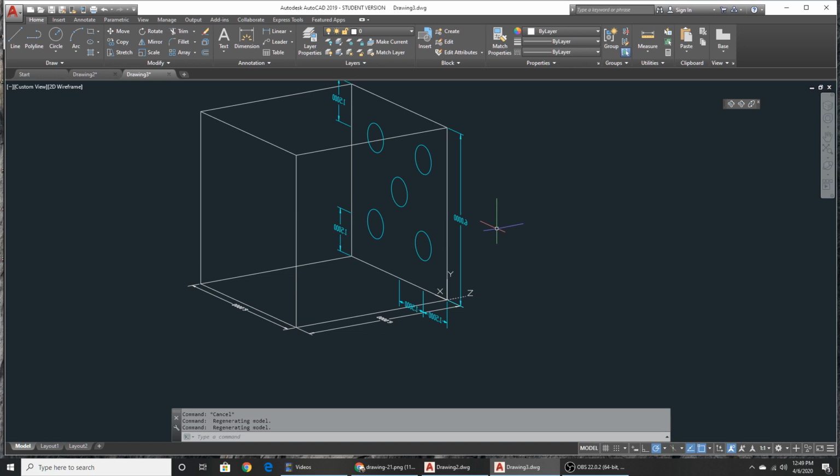I wouldn't want to turn it off yet because I haven't moved my UCS, but let me move my UCS and put it over here. Come on, snap to that endpoint. Waiting for a snap. They're really not snapping anywhere close. Taking their sweet, sweet time. And repeat the process. So offset, the shortcut on the keyboard is just O. It remembers the last distance, so I'll just press enter and do this process again.